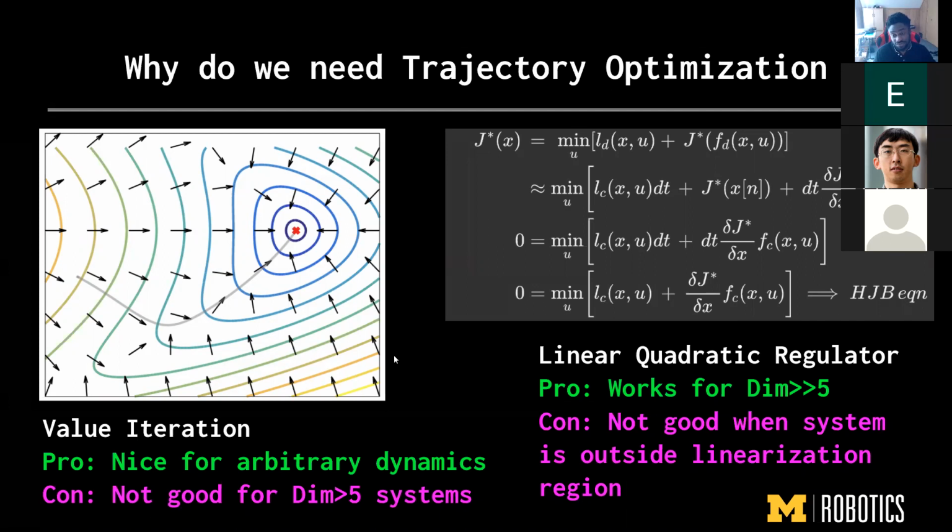So your description of the dynamics of the system should be a linear system, meaning the dynamics equation should be linear, basically made up of some AX plus BU, where A and B are matrices. A represents the states, while B represents the weighting of the controls U. And so we talked about how that was the first condition for LQR. It should have linear state dynamics.